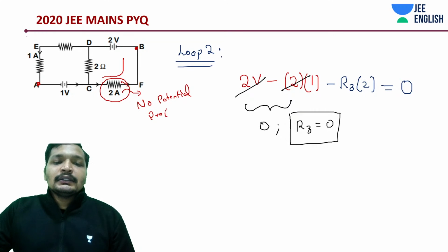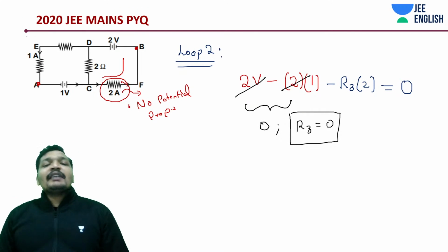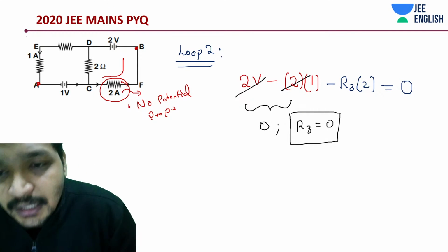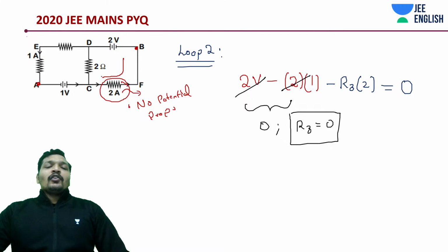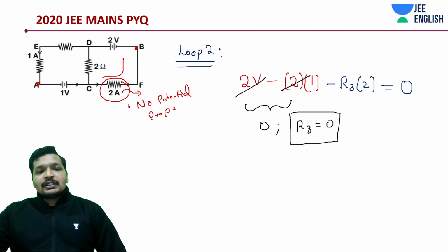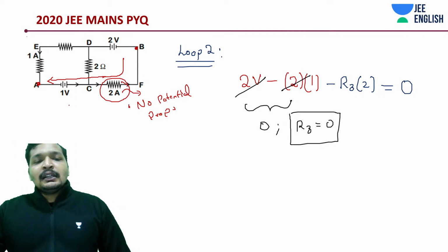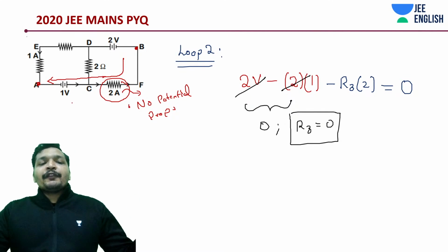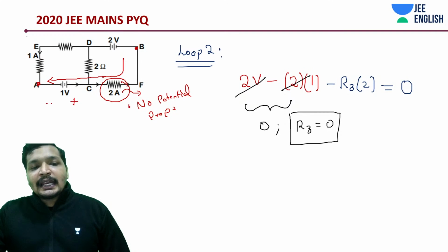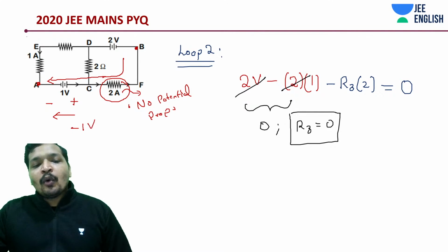That's it. Now, what have we done? First KCL and then KVL. In this case, I'm just looking, already current is given to me. I was looking for the easiest one. So if I move from B to D, what kind of potential am I seeing? This 1 volt battery, but I'm moving from positive terminal to negative terminal. So what should it yield? Minus 1 volt. That's it.